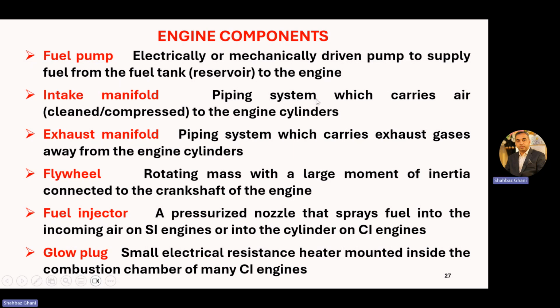A piping system which carries air, cleaned or compressed, to the engine cylinder. If it is an old engine, then it contains an air fuel mixture. If it is a new or latest engine, then there will be piping in which only air is there in the intake manifold. Exhaust manifold. Piping system which carries exhaust gases away from the engine cylinder.